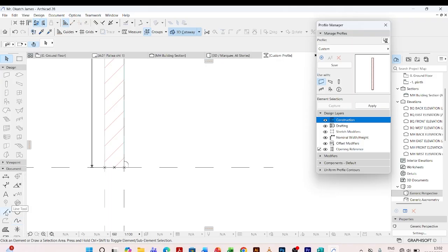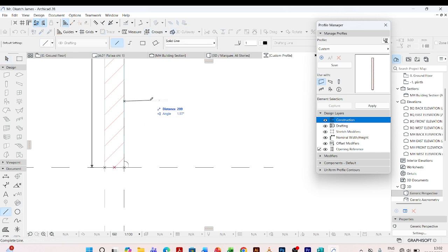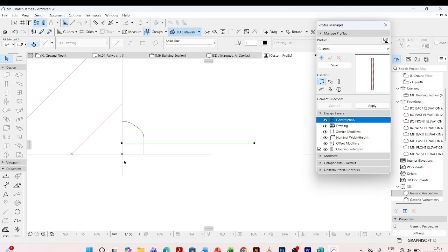So I'll simply come, use the line tool. Maybe I first draw a line here. And come pick this, Ctrl D. First move it down a bit to 0. Ctrl D, I move it to this line. Ctrl D, up 2.5.